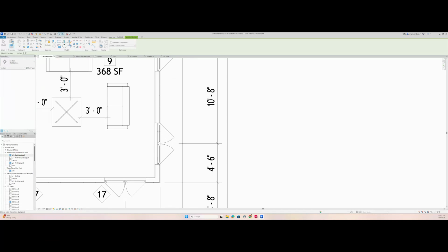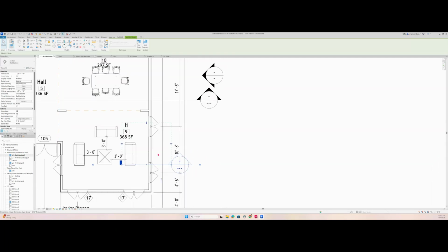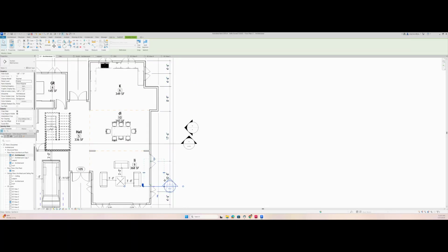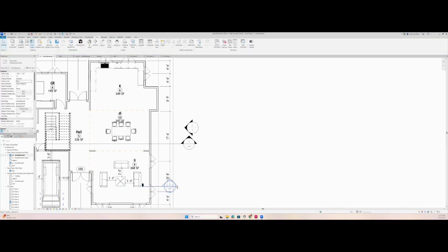And let me go and try to do it through that window, right? There we go. I will make the little fix there. So number one, I don't want it to point that way. I want it to point the other way around. So I'm gonna use those arrows there to move it up, right? I'm gonna move the view range a little bit and the symbol also, crop it a little bit. My view range, those arrows for the view range, they go a little bit further. Got it? So now let's start working with our section here, right?